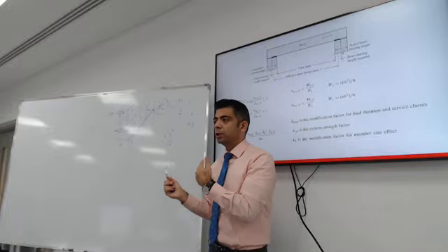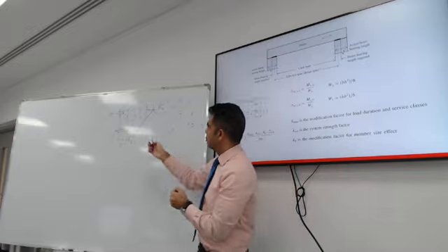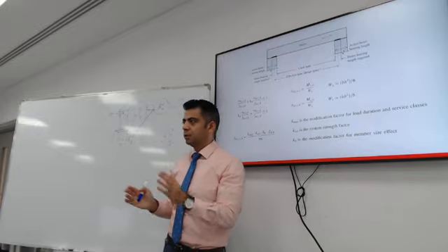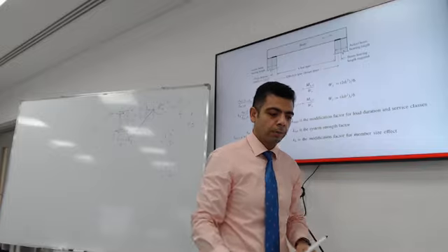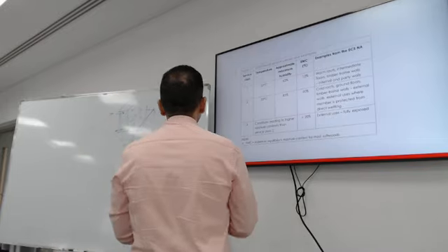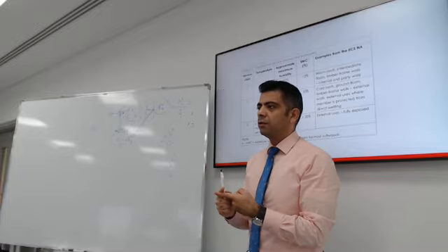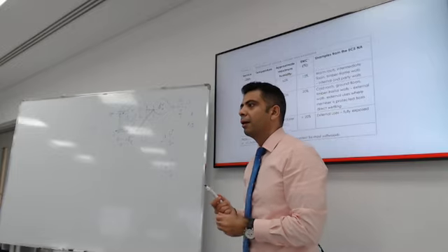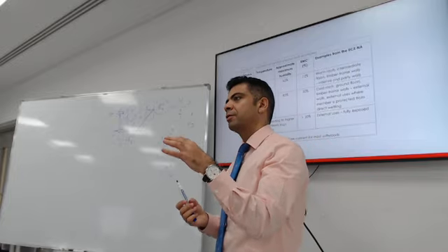All right? So wood doesn't behave like that. Wood, when it reaches the maximum stress, it will rupture. It will have cracks and it will tell you that it can't take any more. There are a few things that you take into account. First thing is the service class. What is the service class of the structure?